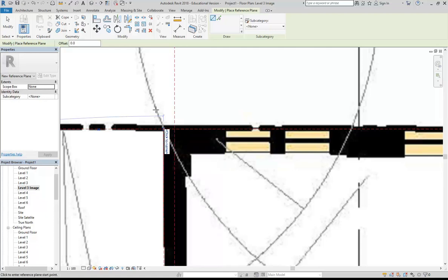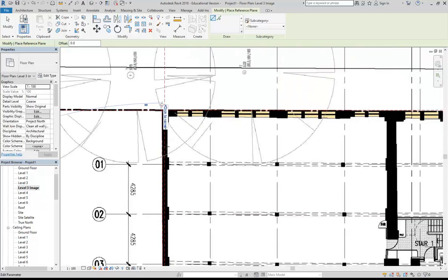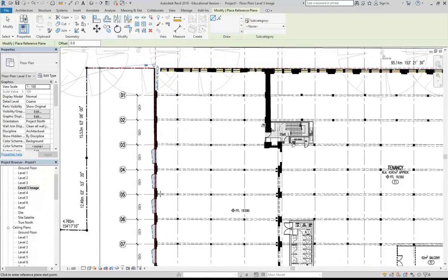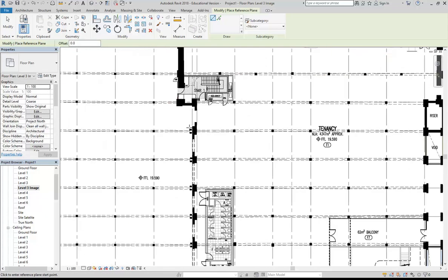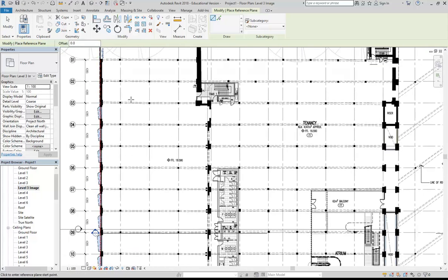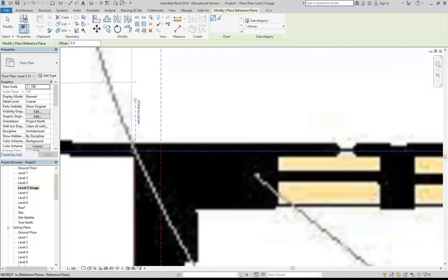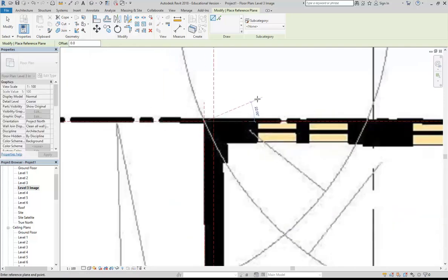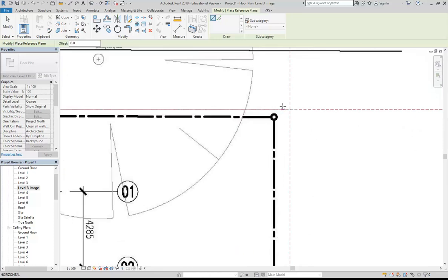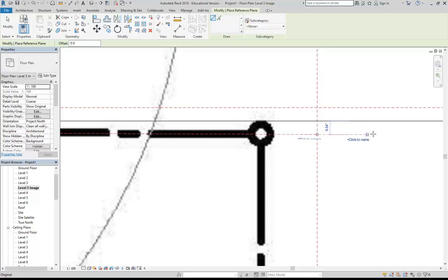So the guys at SJB, a lot of them are interior designers. They've obviously done this, so you should as well. But to give you a tip there, if you get a chance, when you're doing your interior walls, like these ones here, keep them straight. Don't try to always follow that angle from the outside wall. And we'll have grids for that too. And so now, coming from the intersection here, over to the right, and we can get the angle down to the boundary there. So again, SN to snap to nearest, and I can again get that reference plane.